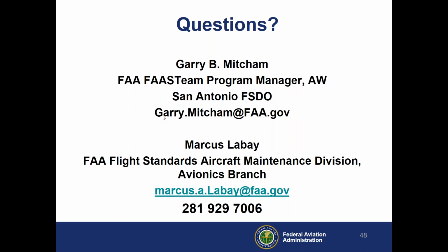I think, Carrie, you had mentioned FlightAware. Yep. I would recommend everyone go to their website. You can download an app and put it on your phone. It works really well. And what I suggest is you turn your transponder on at field elevation to see if you're picked up without any attenuation or any couplers or anything. Then put your couplers on and then see that the signal goes away, that you no longer see your aircraft on FlightAware. It's a good tool to use.